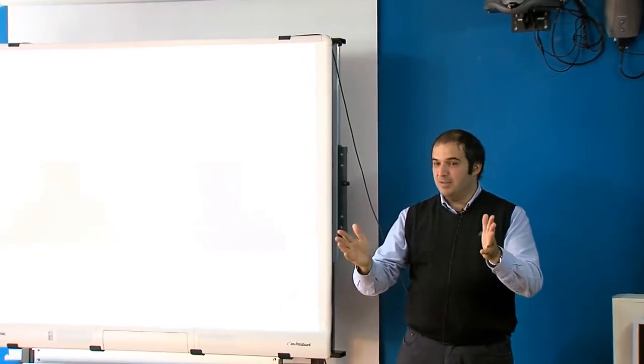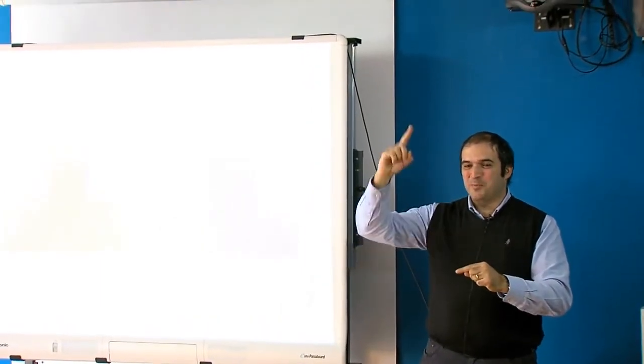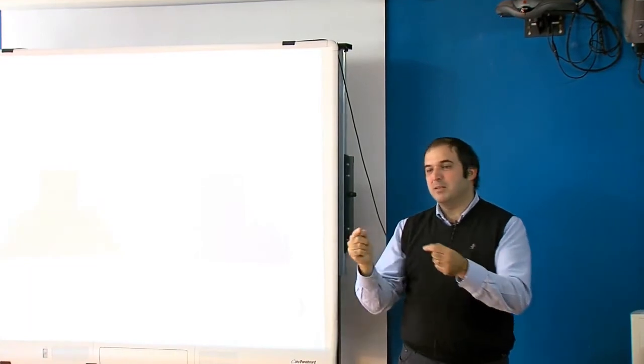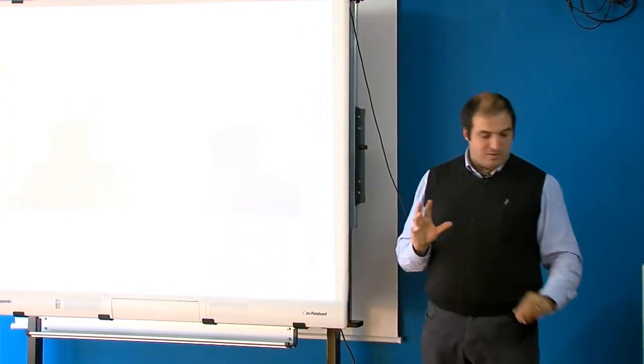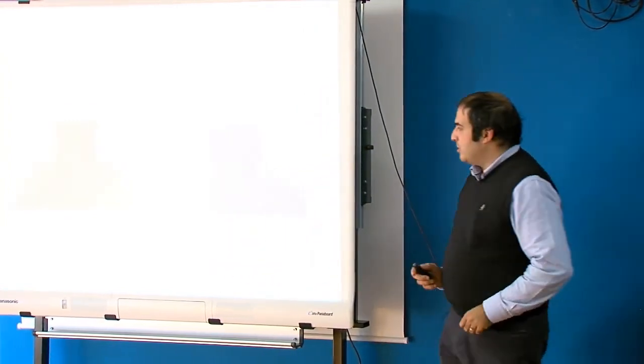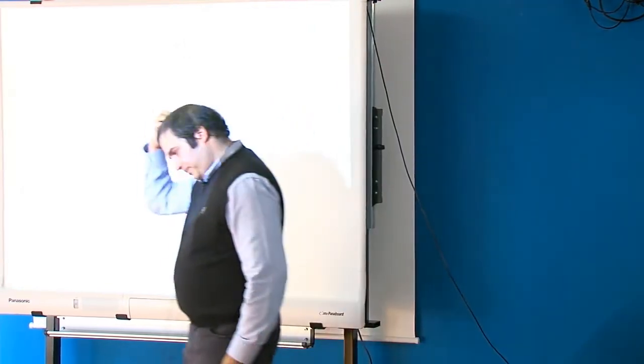So when they start to combine GSM signals, the peaks start to be higher. That means they should use the power amplifier much lower. If not, they will start to compress the power amplifier even if they are using the same average power. This is quite important to consider in this case.